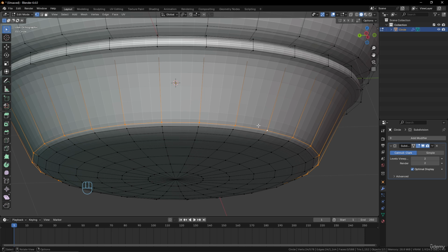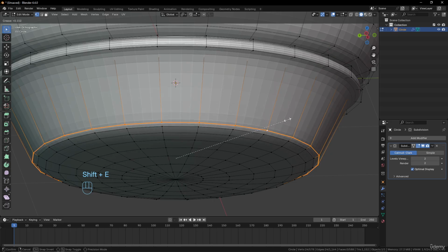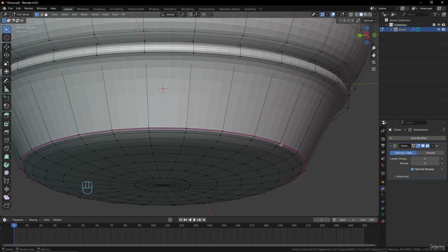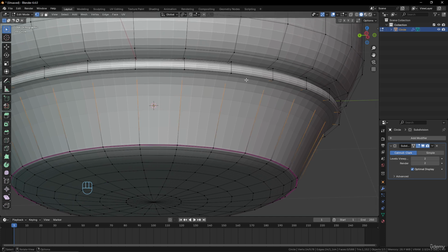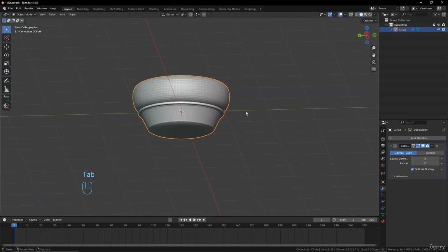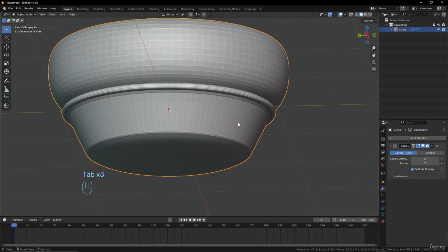We have a specific tool in Blender that works very well. It works only with subdivision surface, and you use Shift E. Shift E will crease, and you can see that it makes the same kind of effect, but only into that selection. Now if I deselect it, it will be a pink color to show that I did crease this one. And I will make the same here. With Shift E, I increase, and look at the right shape that we have now. So it looks good already.